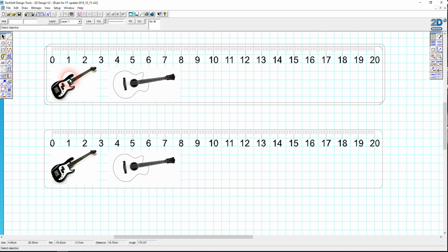So how am I going to fix this? Well, I only actually want to extrude just this, the edge of the ruler. I don't want to extrude into this oblique format any of the millimeter markings, centimeter markings, numbers. So what I want to do is just be able to select the outside of the ruler. Now in my case, I've actually got the outside as a complete path, which makes my life super easy.